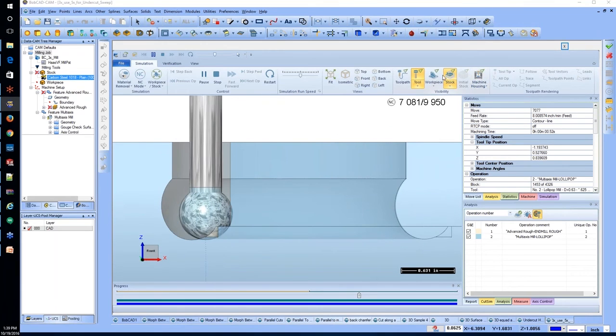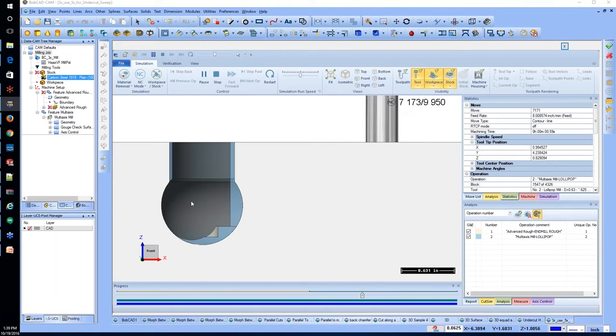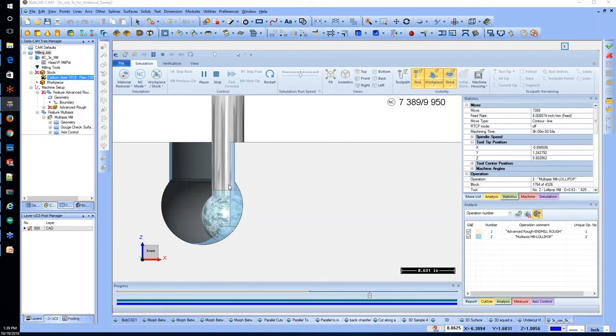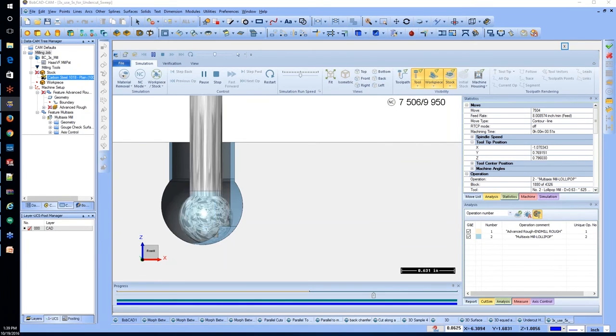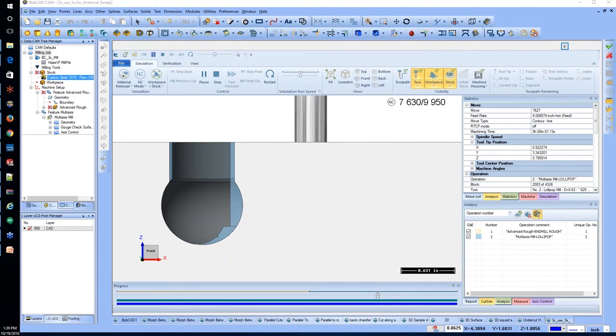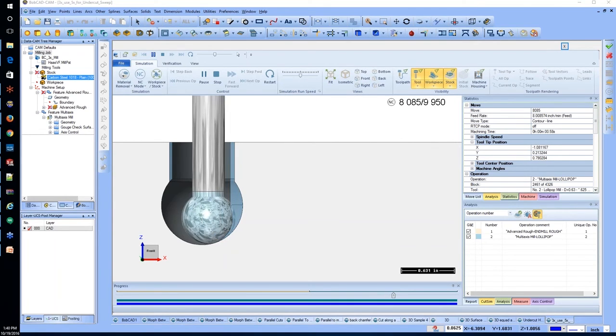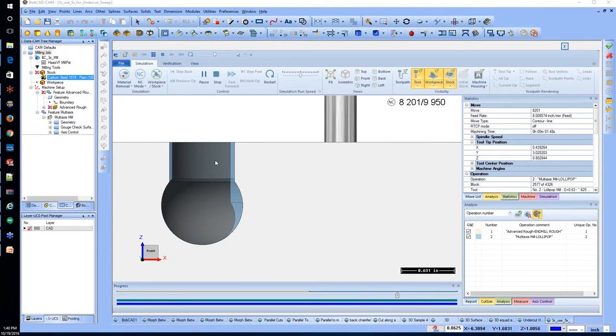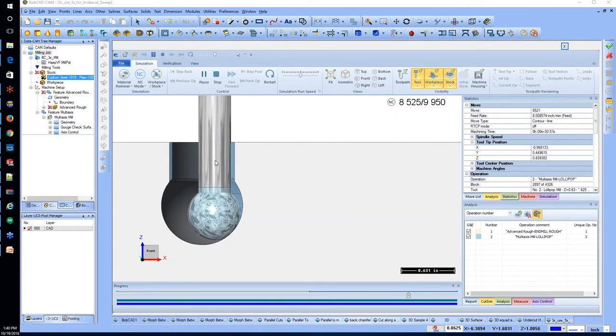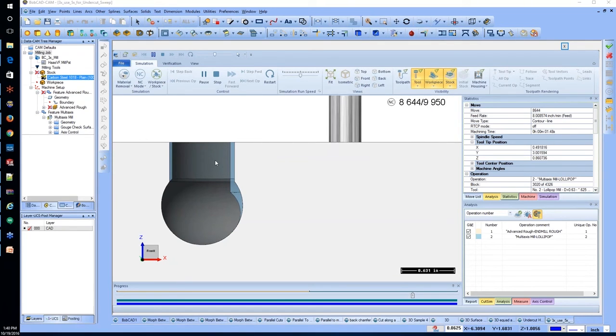Now if you want to see what's actually going on, you can turn on your workpiece versus your stock, and you can see we're cutting the size here, and it's still removing all this material coming up over there. All right. And that's how you actually do undercutting. So if you have jobs where you actually have to output a true undercut, you're going to need the advanced options to achieve what you're looking for. That way you guys can actually do what you need to.